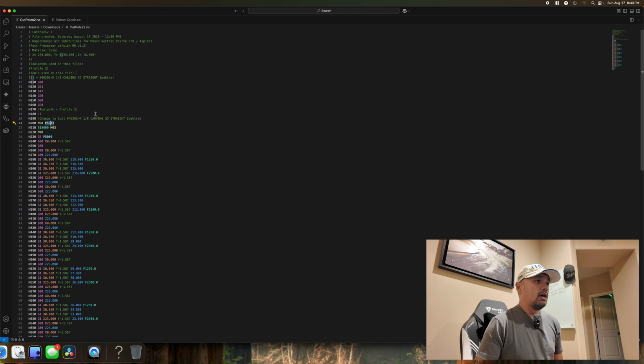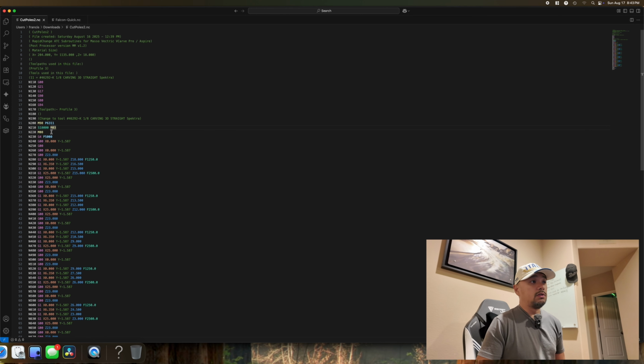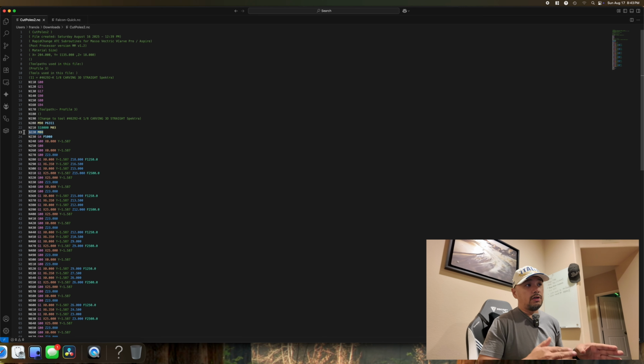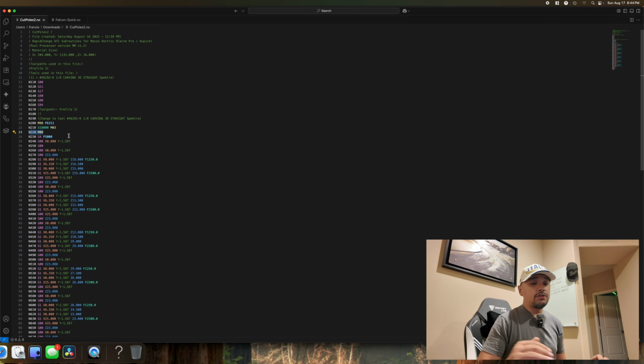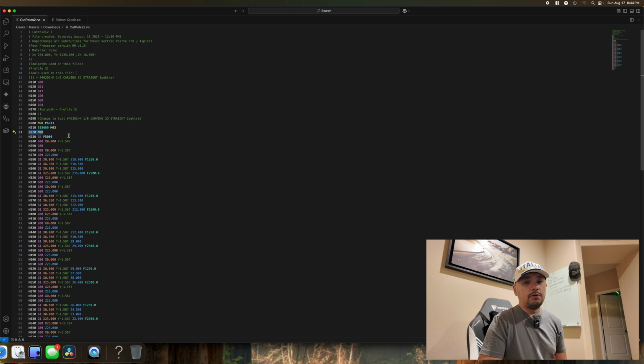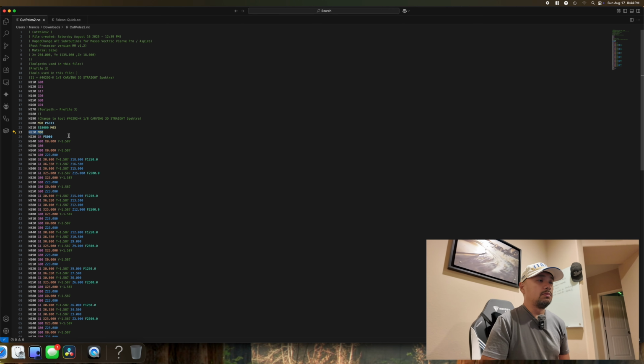The next line is N210, which is S18000, spinning your spindle at 18K RPM, followed by M8. So this is good. It's already issuing an M8 command, which will expand the AutoDustBoot or turn on your vacuum, because both are connected to the coolant plug.